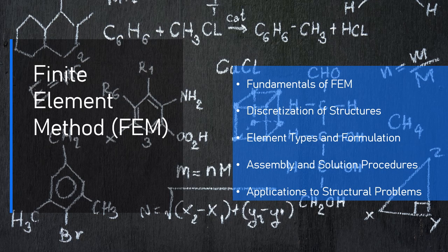4.3. Types of elements in FEM. The choice of element type depends on the type of structure being analyzed. Common element types include 1D elements, beam/bar elements, used for structures like trusses, beams, and rods where bending, shear, and axial forces are important. Example: linear beam elements, e.g., Euler-Bernoulli beam element.